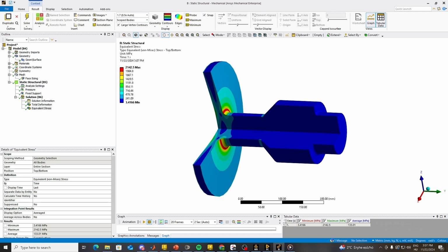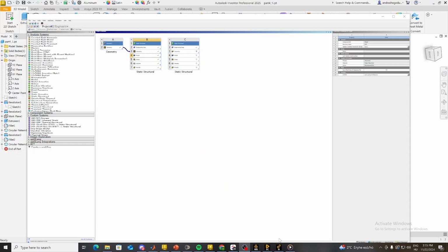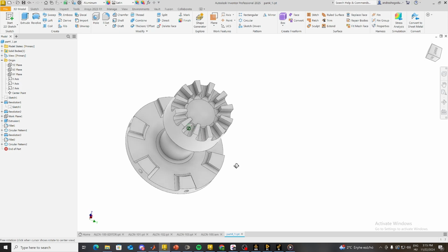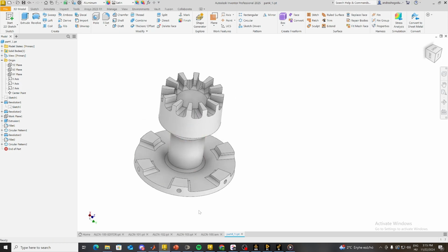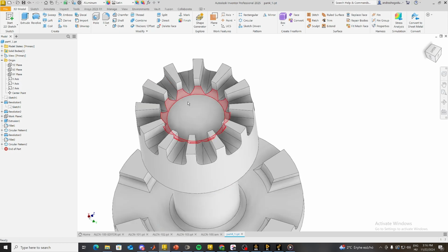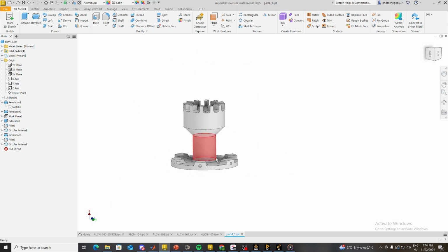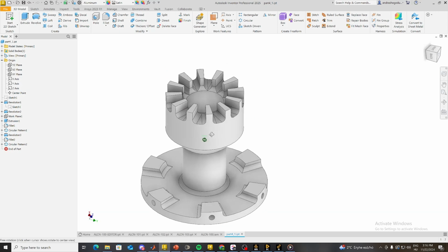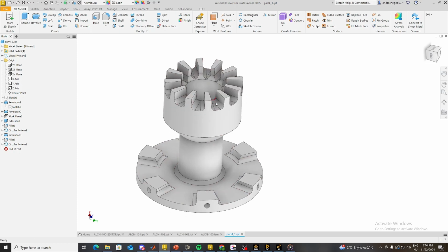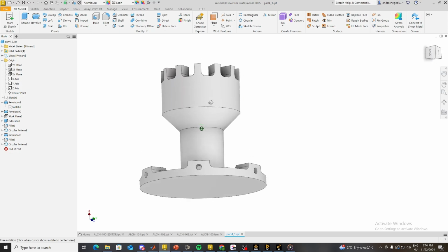That's basically all for how to do the 2D axisymmetric analysis. So now let's analyze a periodic part. Here we see our periodic part. We see that at the bottom side it has 6 patterns, and on the upper part it has 12 patterns. So generally speaking, if we would like to make a periodic analysis of it, we are very lucky because we can, based on the geometry, because 6 times 2 is 12.